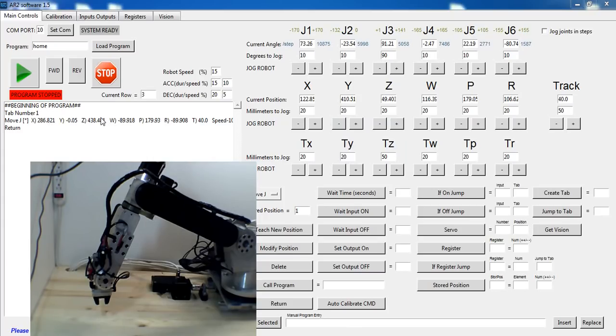So I've converted everything over to Cartesian coordinates. So now when you program the robot, you're programming it in X, Y, Z, yaw, pitch, and roll orientations. That's going to make a lot more things possible. That makes position offsets possible. Eventually that may make it possible to run G code and things of that nature.